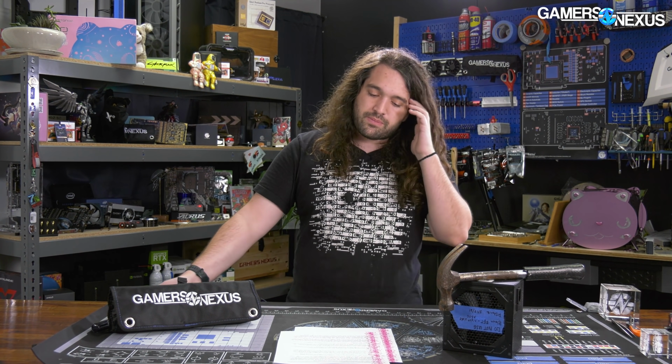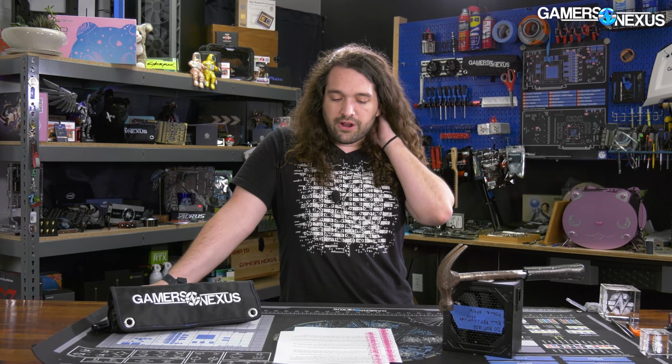Claimed TDP will be in the range of 9 watts to 125 watts, assuming Intel hasn't changed how it evaluates and advertises its TDP number. The thing you need to know is that Intel is typically pretty one-to-one with its TDP wattage number and actual power consumption, not at the wall, but at the EPS 12 volt cable, close enough to the CPU where you only have VRM efficiency losses throwing off the number.